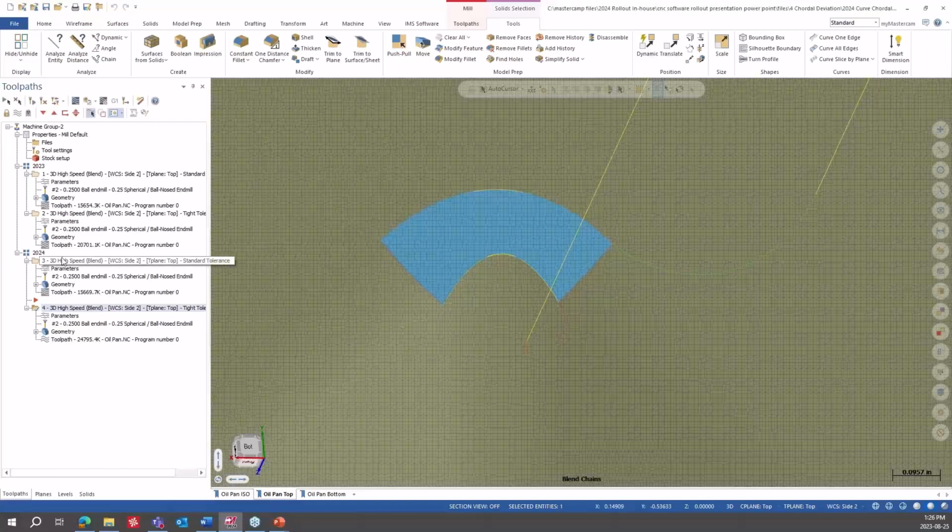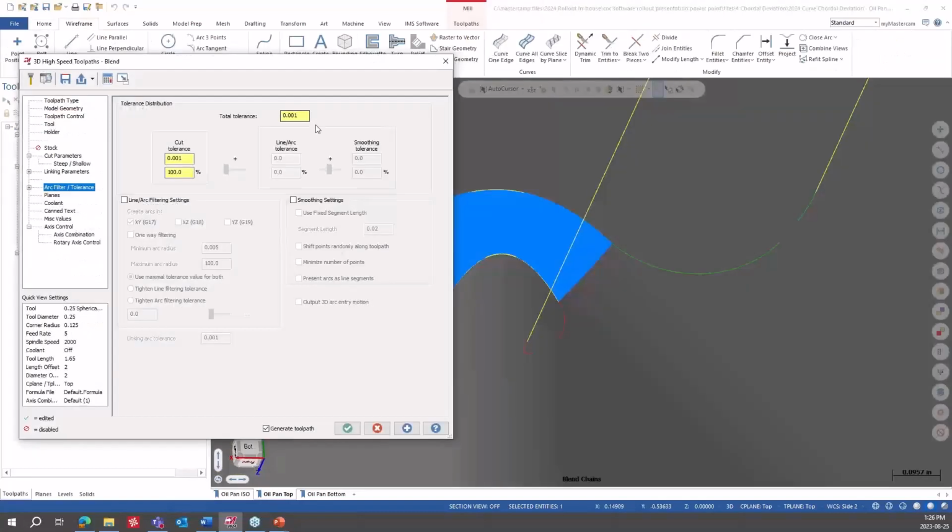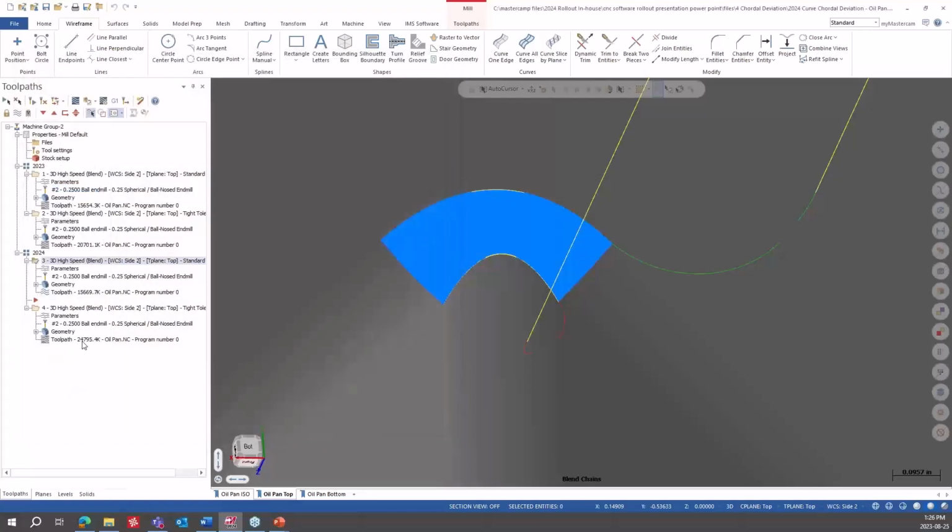You can sort of see that just as an example on the screen here because these are the same toolpaths just calculated with different tolerances, and you can see it's the same step over and everything else. The 1 thou there, and then you can see the difference here. So they're putting in a lot more points by putting the 1/10 tolerance, which follows the curves exactly. So to me, it makes sense that it would absolutely make the toolpath bigger. And like I say, you can see the differences in the sizes there. So I'll move along now.